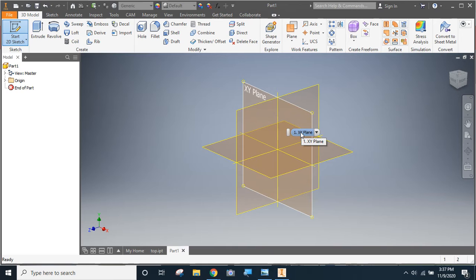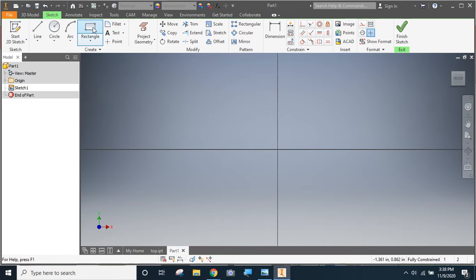The XY plane is the same plane that plywood represents on our CNC router. As the router moves left and right, it's going up and down the X axis. As it moves back and forth away from that computer desk that's sitting in front of the CNC router, it's moving along the Y axis. And as the router lifts itself up and down, it's moving along the Z axis. Just to make our setup a little easier in future steps, we want to start off on the XY plane.